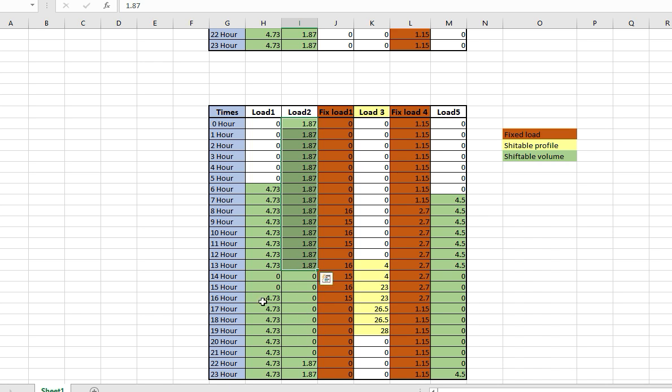The remaining load that cannot be met at night by the renewable energy source will most probably be taken from the grid, as at night the solar is not available and the wind may not be available to feed this. So if sufficient renewable energy is available, it will be used; otherwise we have to take energy from the grid to meet this load demand.